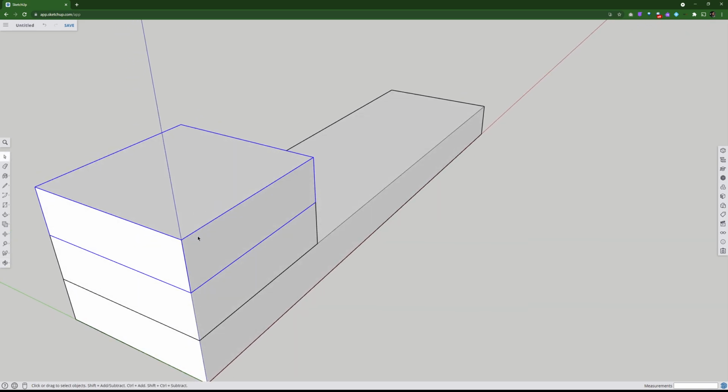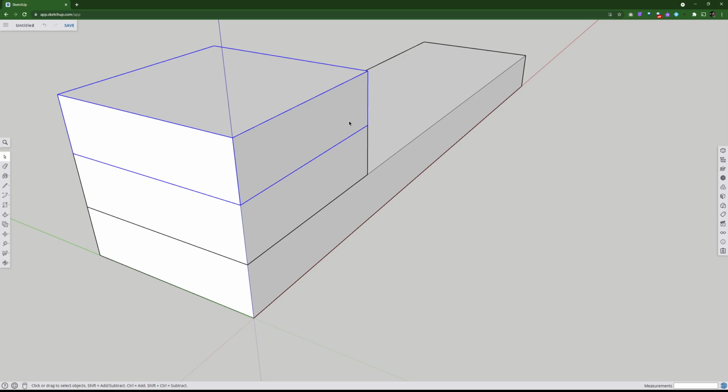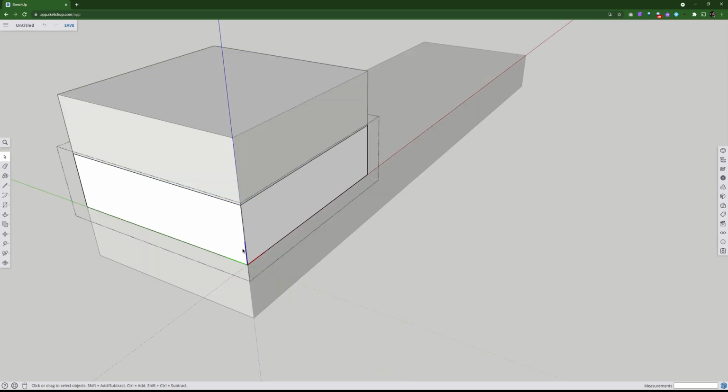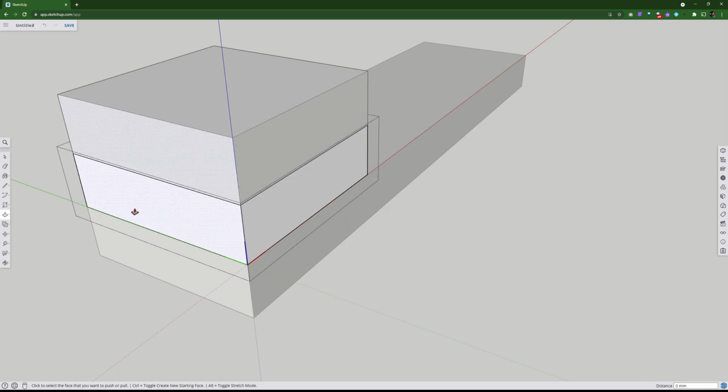Now, if you remember correctly, we disc sanded a little bit off the edge there. So what I'm going to do is edit these pieces. Editing, in the real world, is disc sanding. I'm editing a square to make it something different. I put a little taper on mine. I come in about 5 or 6 millimeters. So I'm going to pick either one of these because they're the same part. I'm going to double click on here, go into edit mode. Now, instead of picking a face and pulling it out, I'm going to pick an edge.